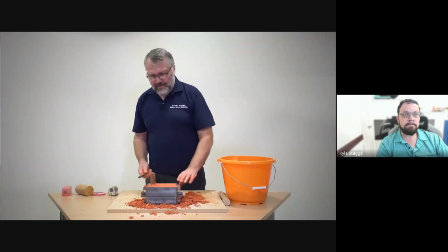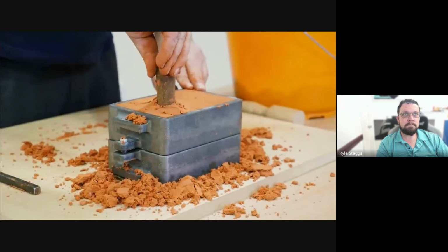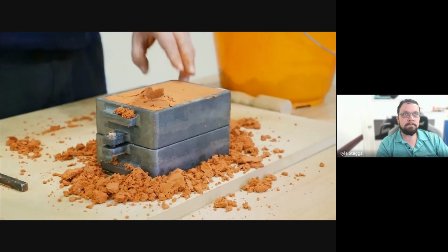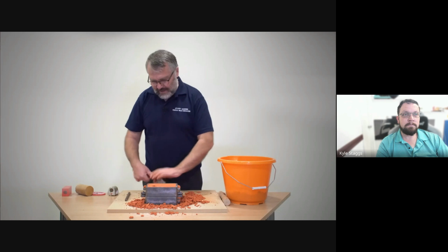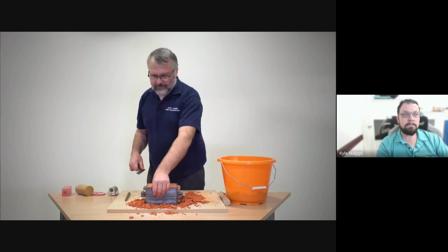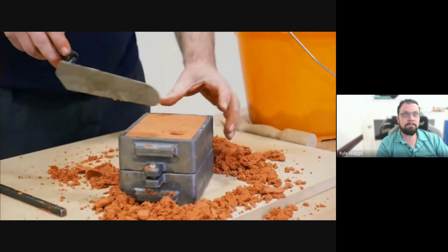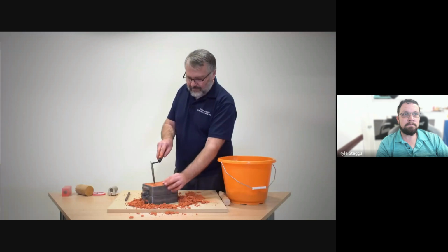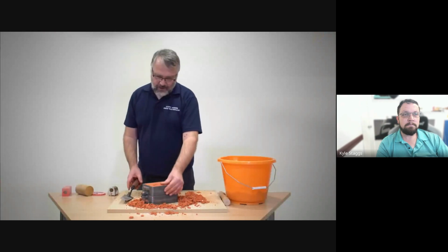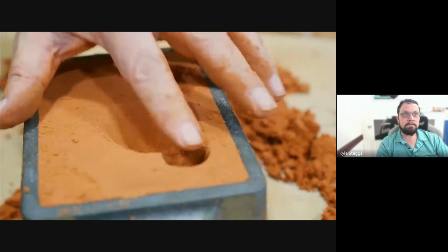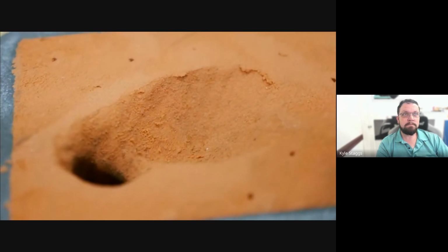And then to remove the sprue pin, we just give it a tap, twist it, and because it's tapered, it releases easily out of the sand. I'm going to use a trowel to take the top off around the pouring hole and make sure there's no loose sand, which would wash into the mould. We also produce something called a pouring basin, which makes it easier to pour the metal. It gives you a larger target, but it also reduces the flow rate of the metal going into the mould, so you get less erosion of the sand as you pour.